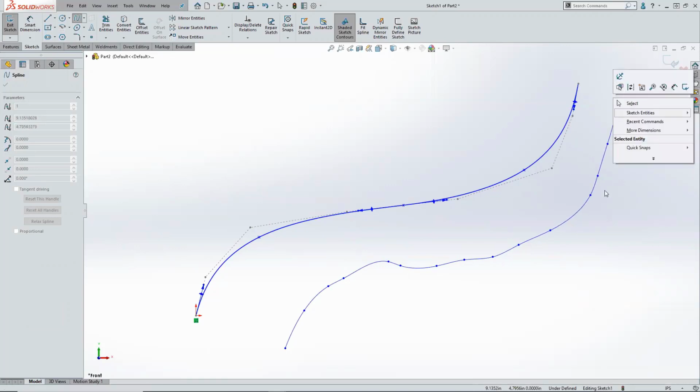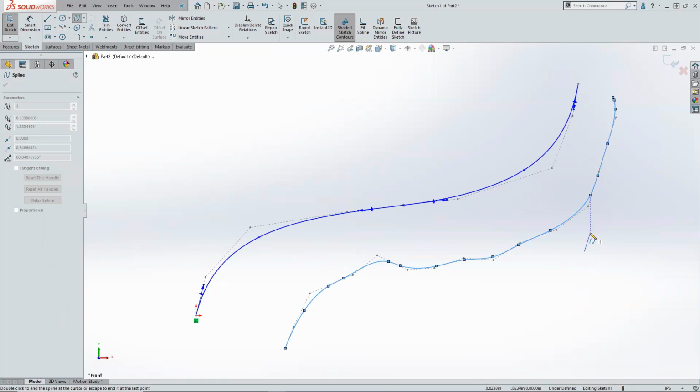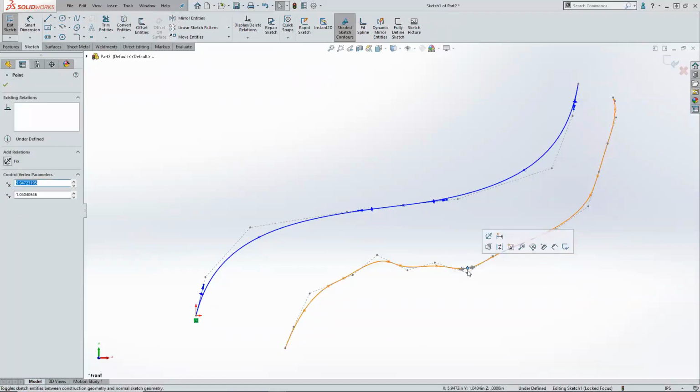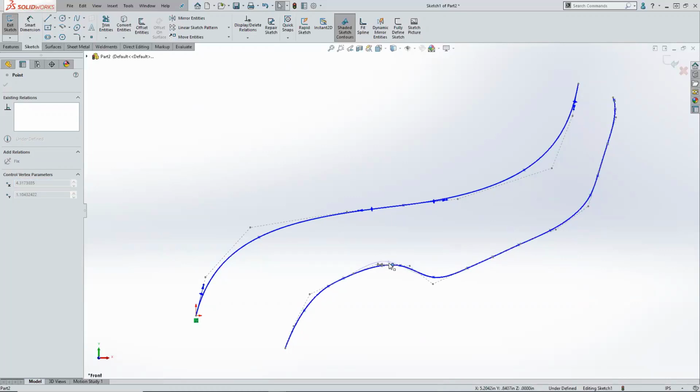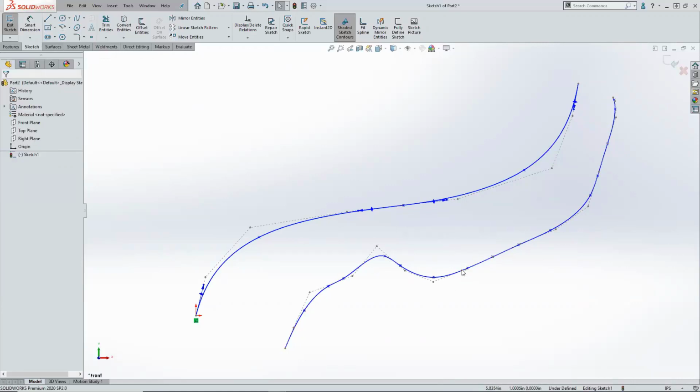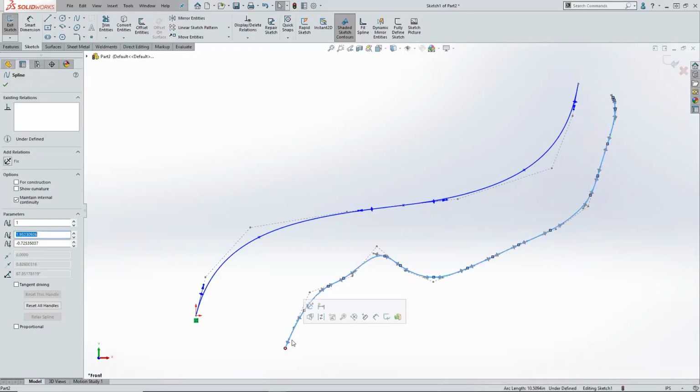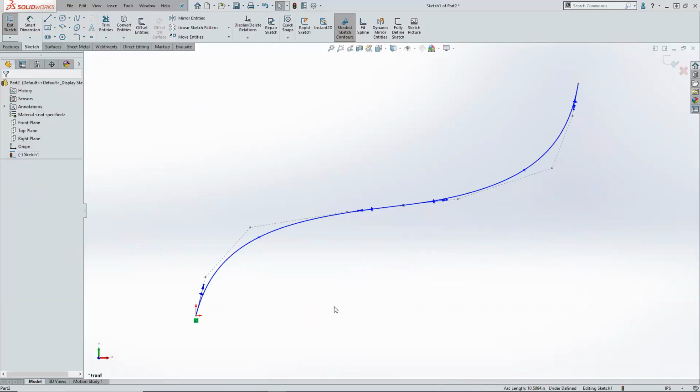to duplicate what I have here, you notice that it's kind of a mess. Okay, well, you haven't seen any mess until you try and straighten this out, because each one of these points then has its own control handles. And again, the control is based around the point where you clicked, that point that you added right there. So this is going to be an absolute nightmare and virtual impossibility to duplicate this curve with. Okay, so the secret to success in using splines is the fewer the better.